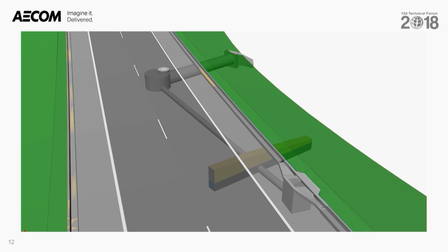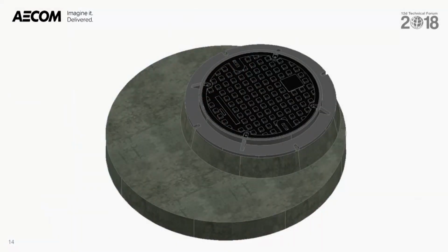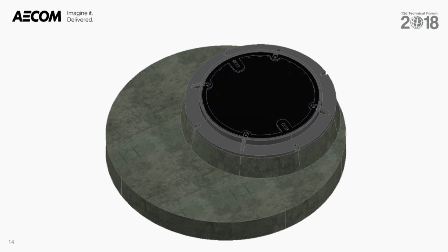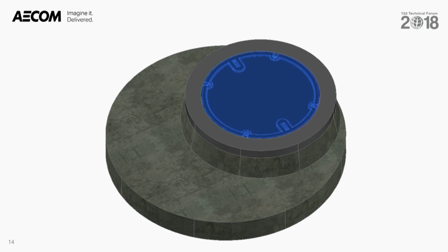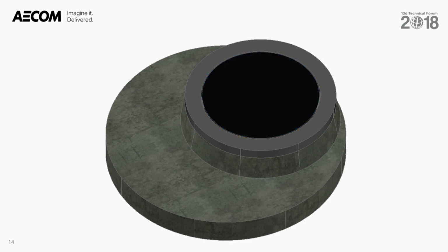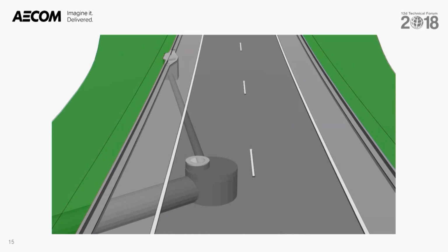This then leads to the debate about what constitutes an appropriate level of detail for a particular object. So if you take up the modeling of the top of an access chamber, for example, does adding the surface textures really add to the value of the space-proofing process? As you continue to work your way through the list of details that do not contribute to the space-proofing function of this object, you eventually get something that takes up the room of the riser and the lid, and which is located where the access point will be relative to the pipe configuration, as this may impact on surface features.